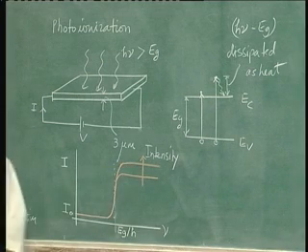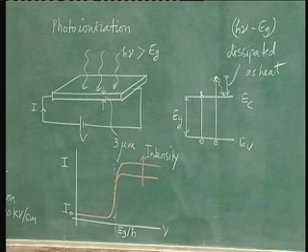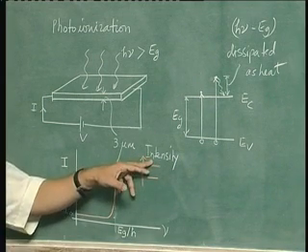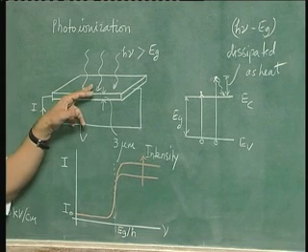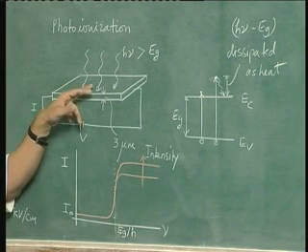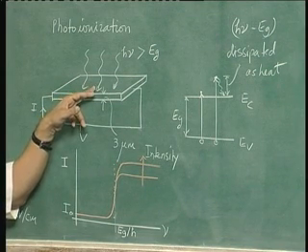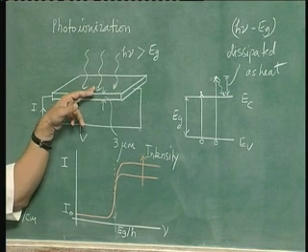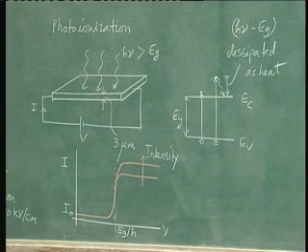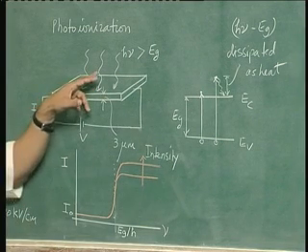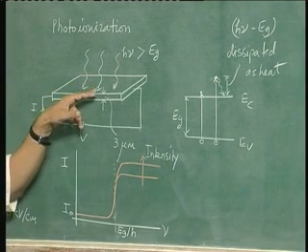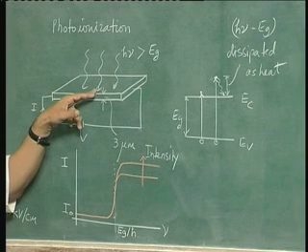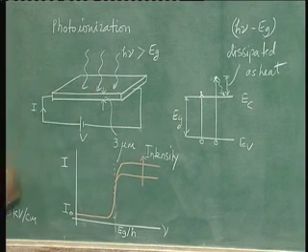So please understand the difference between intensity and frequency. Intensity of light means how many photons are falling on this sample per unit time per unit area. So in other words, it can also be regarded as incident power, okay. Another point to note is that all the photons which are falling on the sample will not create electron hole pairs, because some of the light is going to be reflected, not the entire light is going to be absorbed.